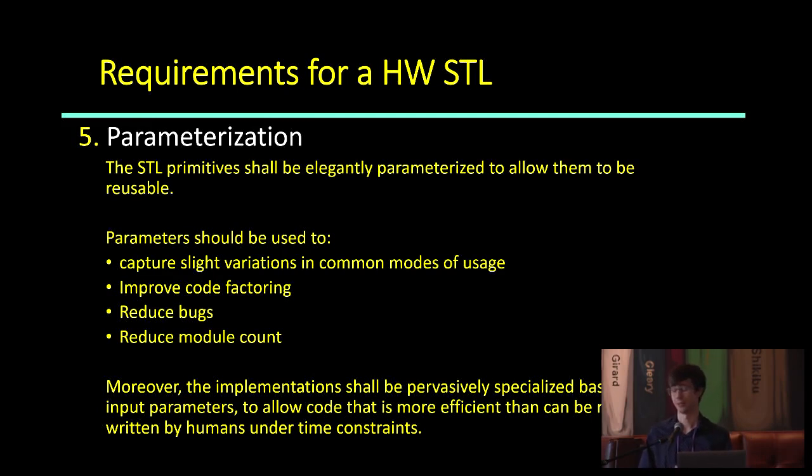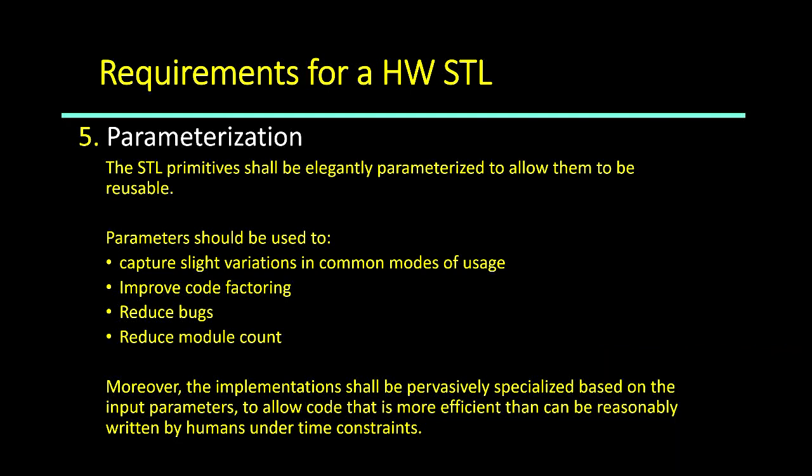And that brings us to parameterization, which is another great technique for hardware programming. This allows you to do simple things like change your widths, but it also allows you at a higher level to reduce bug count, reduce module count by factoring out the common cases and reusing as much code as possible, even internal to the library. This is how we avoid a lot of bugs from re-implementation.